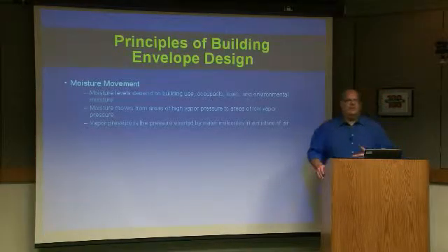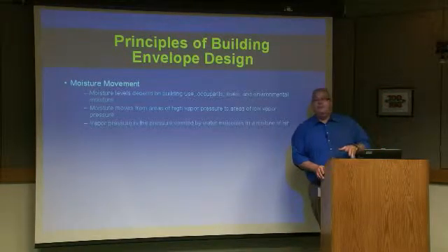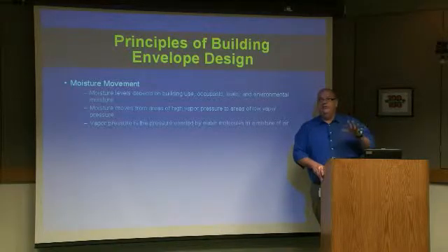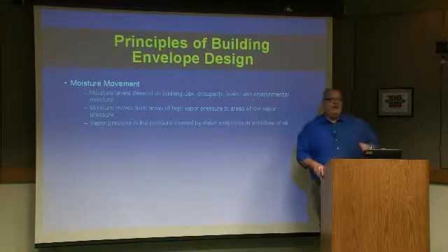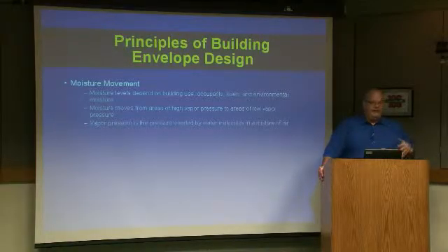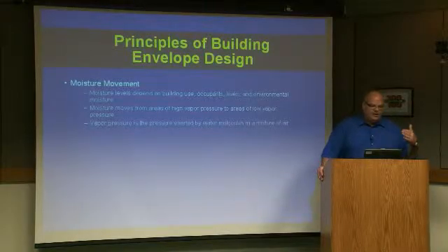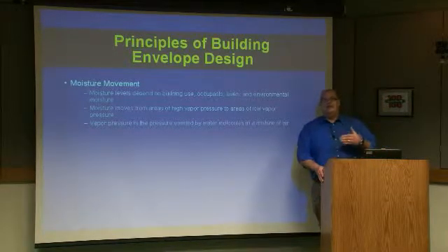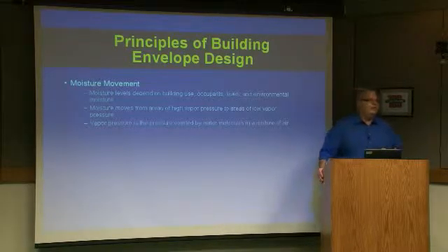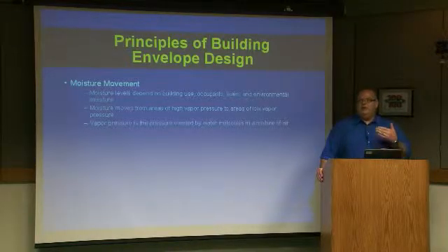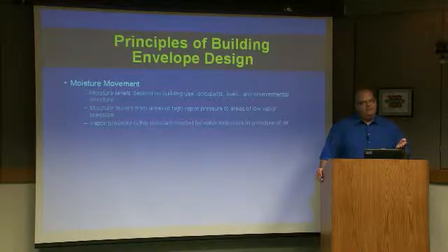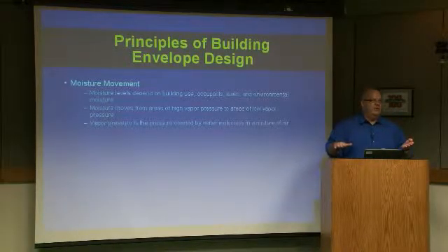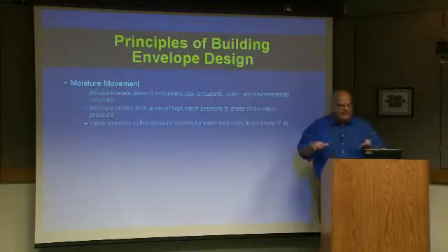Now, moisture movement in general, we did our training earlier this year, we talked about the forms of moisture. In general, moisture is going to move four ways: gravity, airflow, capillary suction, or diffusion. That's going to redistribute the water. A lot of what confuses people in making predictions about moisture movement, though, is the form of water vapor. Water vapor and the misused concept of relative humidity that we get in the news every night explaining what the weather is going to be tomorrow totally trips us up, because the world is reacting simultaneously to relative humidity and absolute humidity. And they're two different things, and materials behave differently around them.